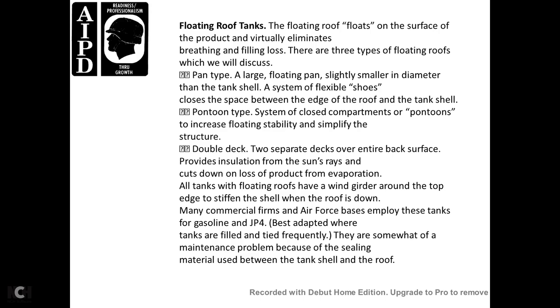All tanks with floating roofs have a wind girder around the top edge to stiffen the shell when the roof is down. Many commercial firms and Air Force bases employ these tanks. They are best adapted where tanks are filled with gasoline or JP4. Frequently they are somewhat of a maintenance problem because of the sealing material used between the tank shell and the roof.